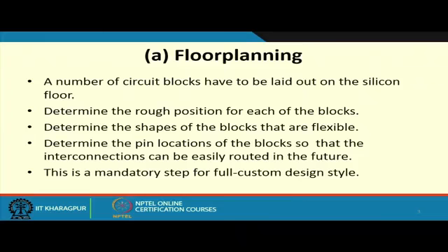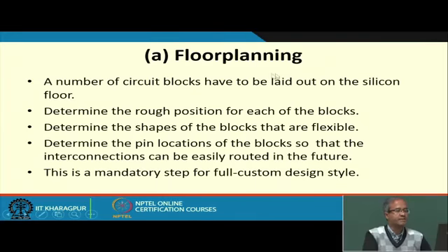Let us start with the first step, floor planning. Floor planning, what does it mean? A number of circuit blocks have to be laid out on the silicon floor. Determine the rough position of each of the blocks, determine the shapes, determine the pin locations. I have mentioned a lot of things. Let us talk about an analogy, you will be able to appreciate it better.